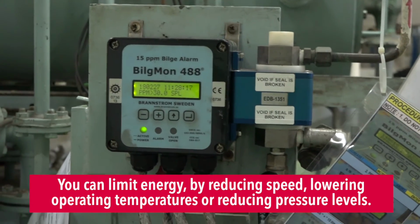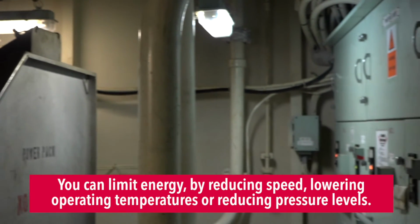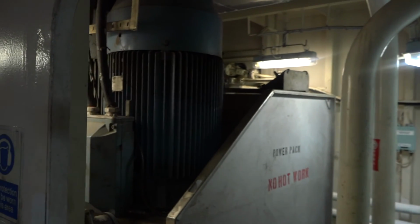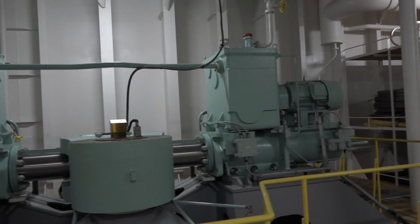Thirdly, you can limit energy by reducing speed, lowering operating temperatures, or reducing pressure levels. The next best thing to do is provide barriers around the energy source, such as electrical and thermal insulation, guardrails, containment systems, detection sensors, and shutdown devices.